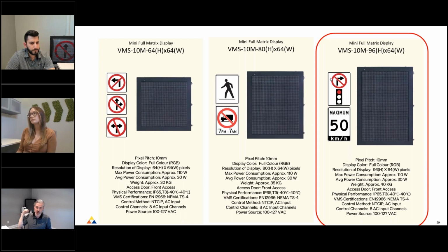The difference with a BMS sign is that they come with uniform modules. In this one, there's 3 across, they're more square. The ones Harrison had are more rectangular. But you have, call it, a matrix of 15 LED modules. So if you have an LED failure, you can open this up, and in about 10 minutes, unscrew and remove that LED panel, insert a new one, screw it back in, plug in a power and communication cable, and the sign is fully functional again.